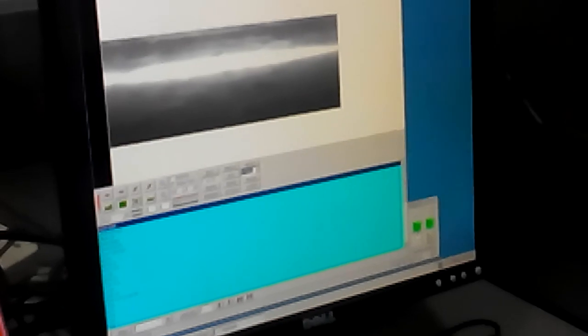Before, when you pressed auto and cycle start, it was only showing the simulation. At this time the machine is going to run. When you press auto and cycle start here, cycle start, now the machine starts, the program runs. That's how you do this.